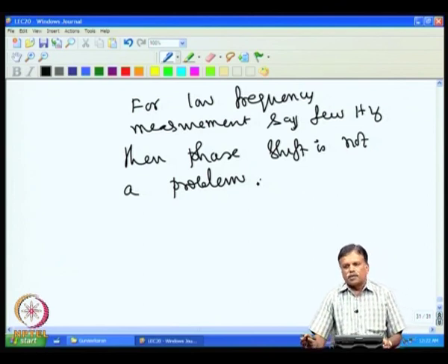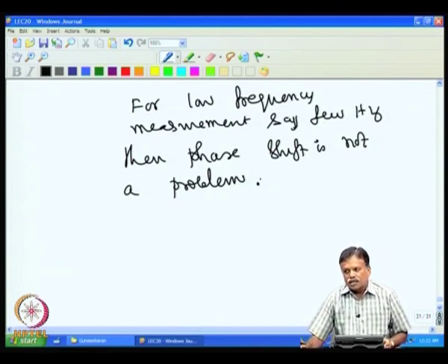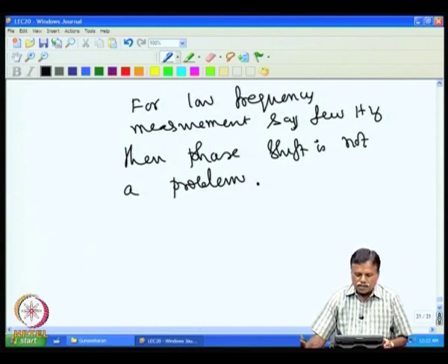So, one can use the op amp for automatic balancing, and of course, you will have to measure V1 and V2 to make the measurement accurate, and keep the frequency of the measurement low, so that the error is small. So, this is how high resistance measurement can be made, which is not susceptible to leakage resistance and so on. And this method is very popular and is extensively used, like the ratio transformer technique. Next class you will see the other issues of the bridge method.